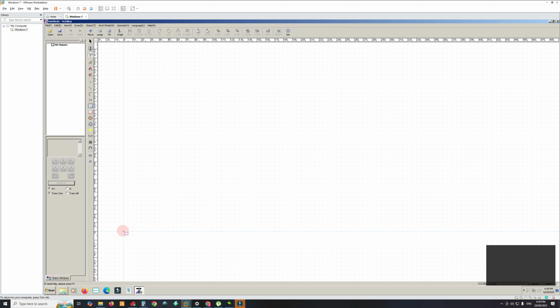It makes it easier when we are having to calculate using maths where we're going to put each line and all that sort of stuff. For a basic benchtop, you don't really need to add anything, but we're still going to start at the zero point. Makes life easier. So just a quick note as well, after every step just about, I'm going to tell you to right click, escape. It's a bit of overkill, but it makes sure that you haven't left anything else selected before we start the next operation.